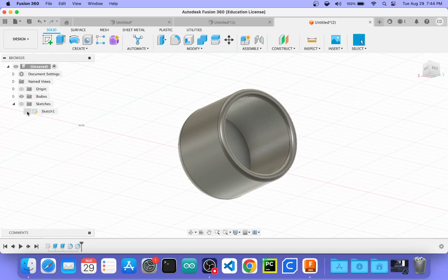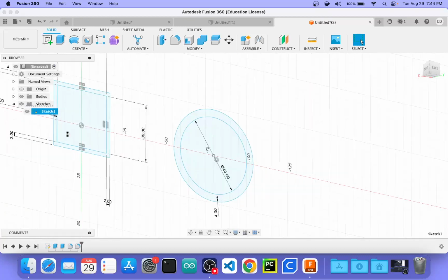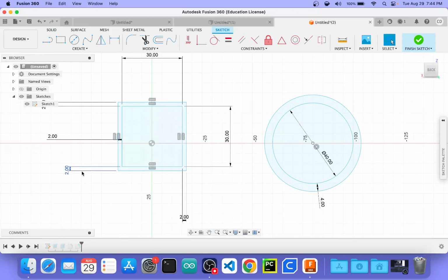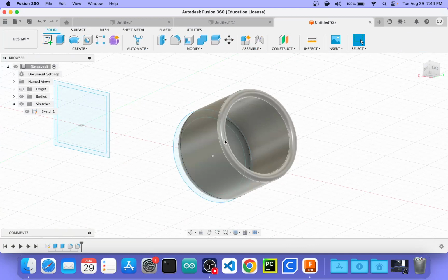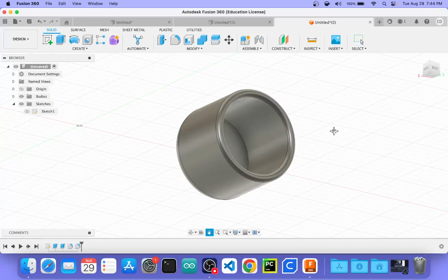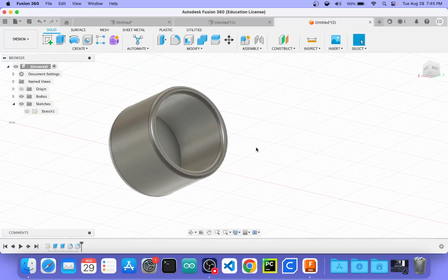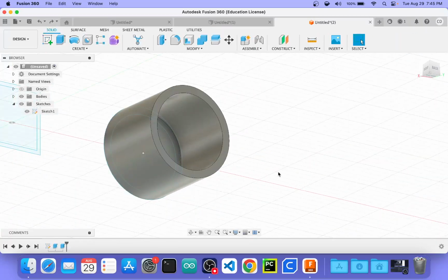So a couple of things I want to reiterate on this is in this sketch, I used relative dimensioning to make sure that there was a specific amount of space between these two shapes. When I finished the sketch, I went ahead and extruded a couple of different parts. This is something you've done, controlling sketch visibility, so that I could actually get everything I needed. And then the other thing I want you to take away from this first part is you can multi-select. So I'm going to, let's see, I'm just hitting Control-Z to roll back. I could roll back the timeline.